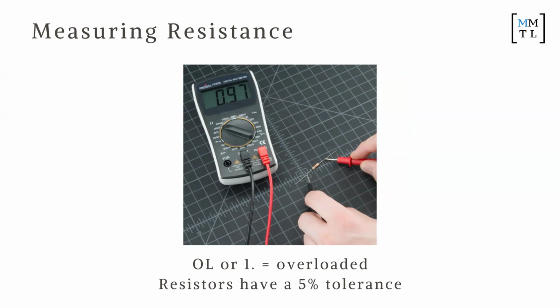For example, if I want to measure up to 1,000 volts, then this is going to give me like 200 or whatever. Because we're not operating at that level, we're operating at 5 volts, I've set it as 20 because the next one I believe is 2,000 millivolts, which means 2 volts, so it's going to be too low to read. If I try this, it's not going to break the multimeter or anything, but it's probably going to say 10 is my guess.